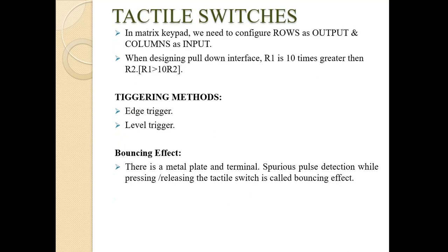Now let's see about the tactile switches. In a matrix keypad, we need to configure rows as output and columns as input. When designing a pull-down interface, R1 is 10 times greater than R2.